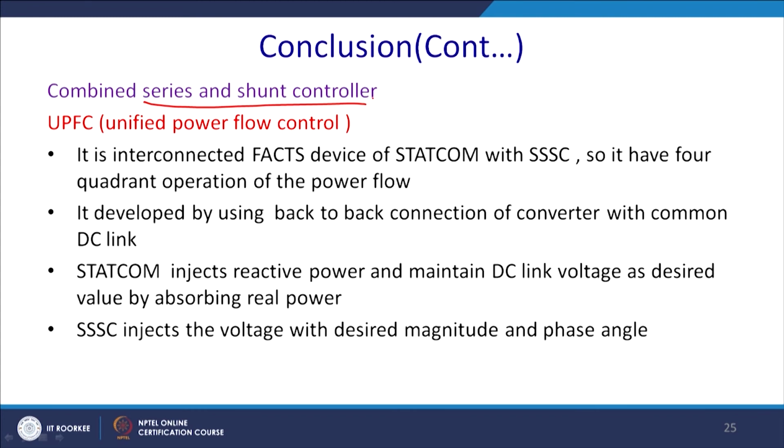From there we have the most modern compensation technique, that is UPFC. It is an interconnected FACTS device, a combination of STATCOM and SSSC. So, it has all four quadrant operations of power flow. It is developed using a back to back connection of converters with a common DC link. STATCOM injects reactive power and maintains the DC link voltage as desired by absorbing the real power.